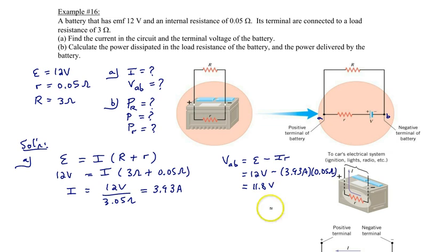And you'll notice, by the way, this terminal voltage is not going to be constant. The higher the current, the more that potential drop is going to be lost within the battery, and the less you'll get available outside. And the higher current will depend on what that load resistance out here is. So if R, that load resistance, gets smaller and smaller, then the current that's driven through the circuit is going to get larger, and so there'll be less voltage available externally on the terminals.